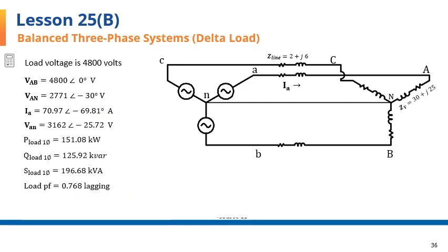And here they are. I'll next calculate the single line power loss, the power loss in the lines, but just for one of the lines, by multiplying the square of current times the Z line shown in this equation here. S of line for single phase is magnitude of I squared times Z of the line.